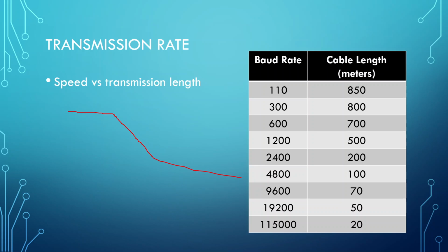Because of that transition period, and that capacitance getting larger with longer wires, we can't take a reading as often. If we took a reading right here, it'd be in that gray zone, and we'd be going, what does that mean? So we'd have scrambled data is what it comes down to. So length is really important when it comes to your baud rate.